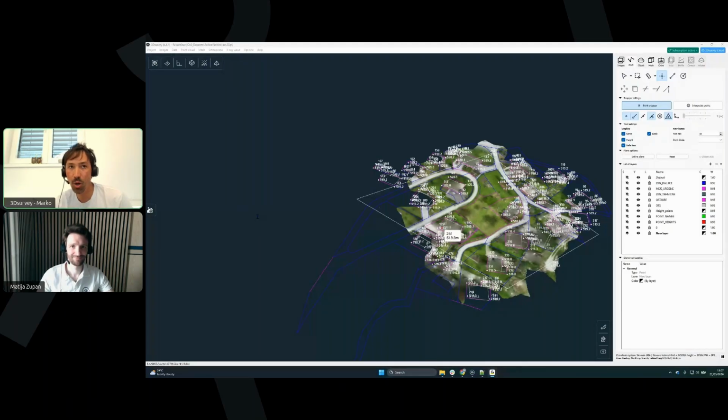Actually, as long as we have good data written in telemetry, so this means if the drone loses RTK connection and in the telemetry it's written that this is not a centimeter accurate position, that this is 5 meter accuracy, it's not a problem for the software. We handle all this. The images with the accurate telemetry will be more important for orientation than images with the worse telemetry, and this works perfectly nice. So I believe there shouldn't be any problems.